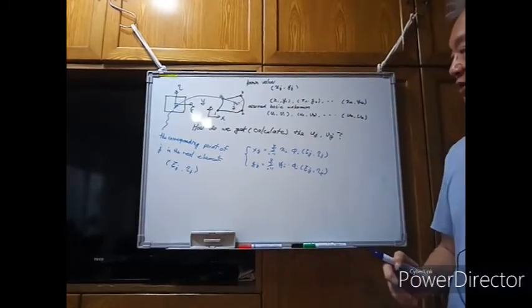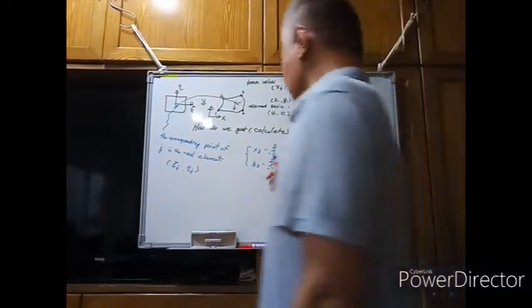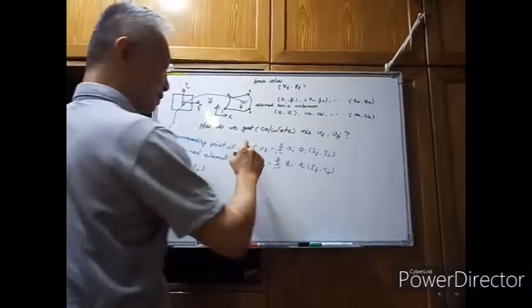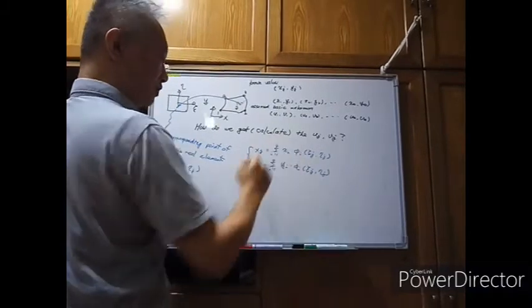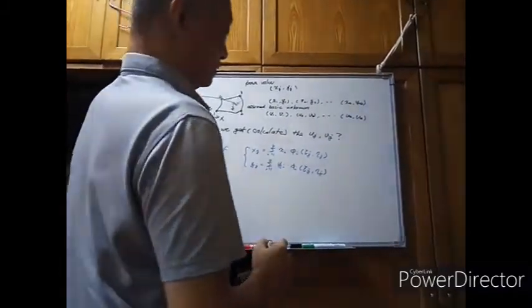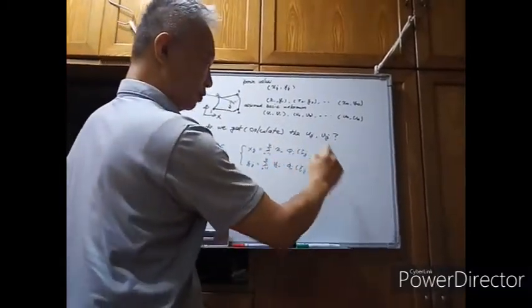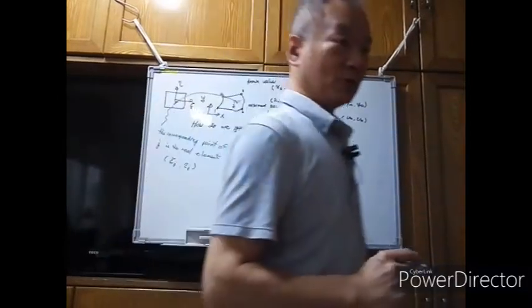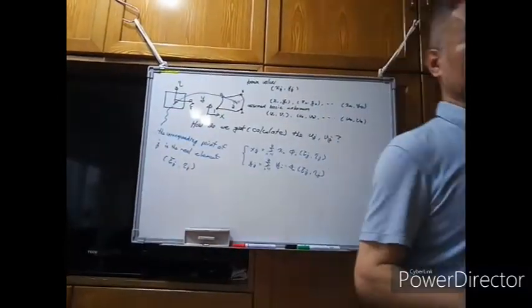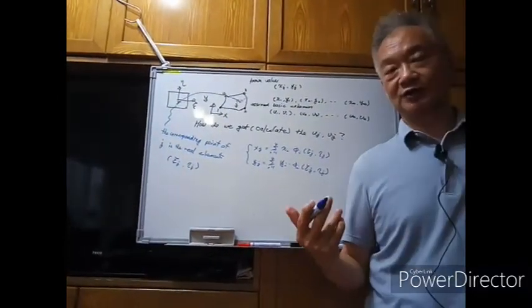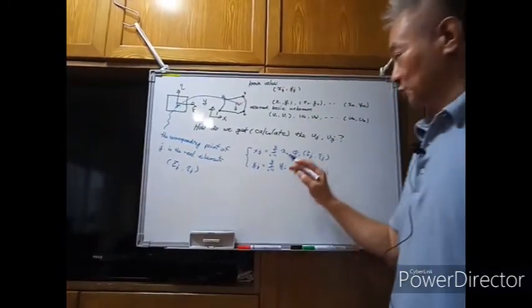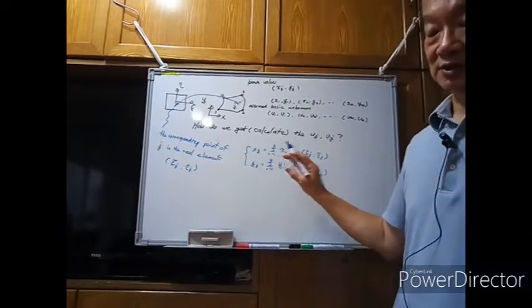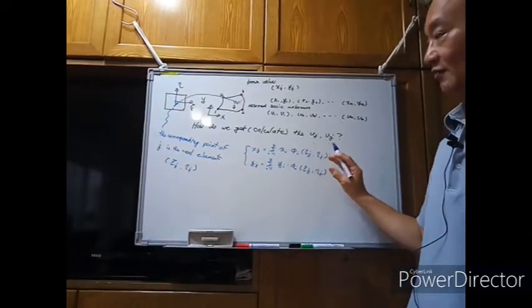And right now we know the xj and the yj. Also we know all of the xi and the yi. And also we know all the shape functions. No matter whether you use the 4-node element, 9-node element, or 16-node element, the shape functions can always be developed.